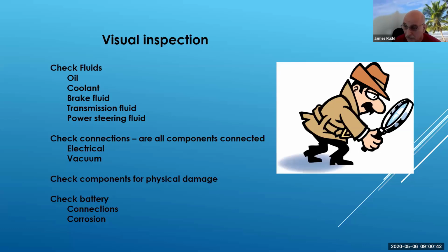Battery, check the battery, the connections, corrosion, in the engine performance world. If we have low voltages, it can actually affect all kinds of things going on. So your battery connections are very crucial on getting current to the different components, and to the computer too.